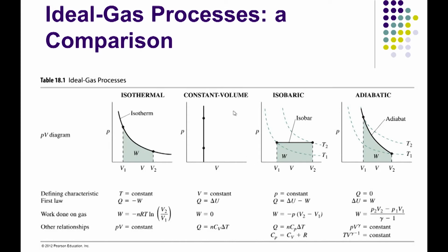Now, if you look at the constant volume, what happens then? There is no change in the volume, there is no work done. So it is a straight line in the PV curve. We are always looking at the P versus volume curve, and as you know, the states of the thermodynamic variables can be defined by 2 variables, and normally they are a multiplication of an intensive and an extensive variable.